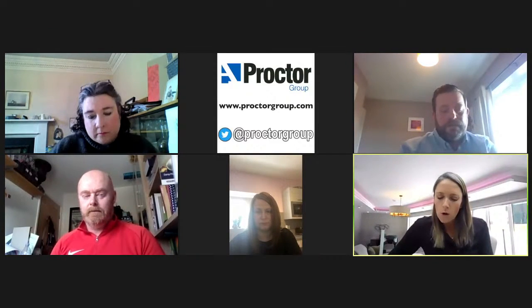And Chris, if I can come on to another one, which is quite specific, from Hannah, please. Why does BS 8485 ask for a thickness of not significantly less than 0.4 millimeters and weight of 370 grams per square meter for gas membranes? Do you feel this is a relevant statement when looking at robustness of membranes?